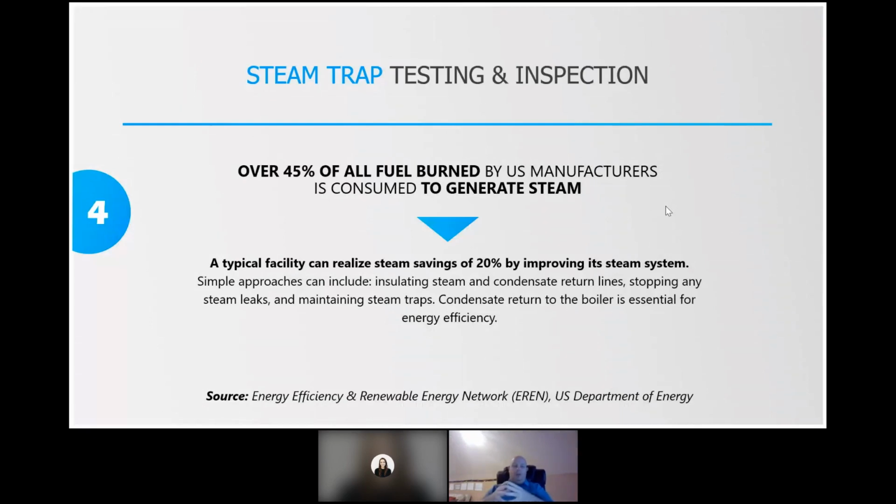Another simple initiative to improve the efficiency of your steam system is just by simply insulating the pipes. If you drive into your plant, and again, just to give you a good visual, look at the roof line. If you see excessive steam venting to atmosphere, it's usually a good indicator that you have some failed steam traps on your system. Typically, they're going to be failed open.